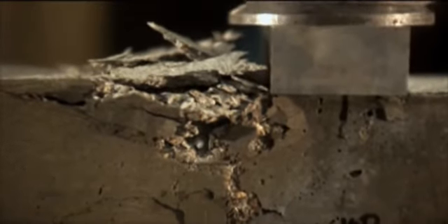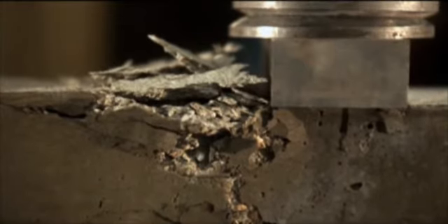This is an undesirable mode of failure since failure occurs in a brittle manner without significant warning rather than in a ductile manner. Ductility at the ultimate limit state is desirable since it gives plenty of warning that elements are being overstressed and also aids redistribution of moments in continuous structures. Therefore, beams should be designed so that the ductile steel yields before crushing failure of the concrete occurs.